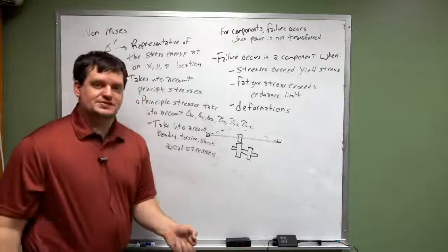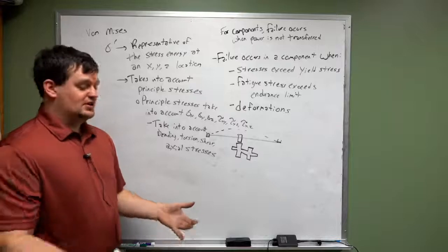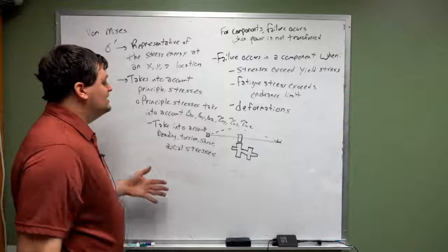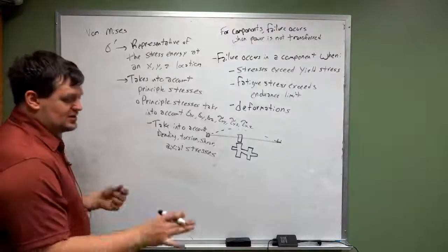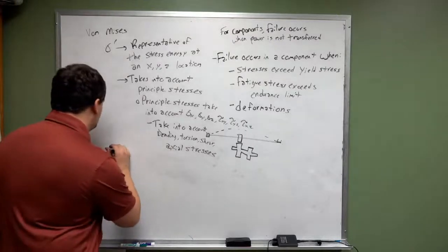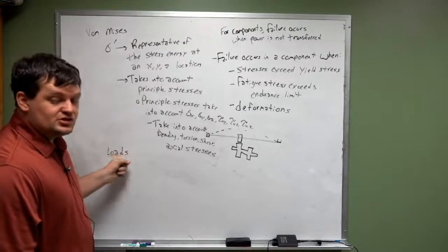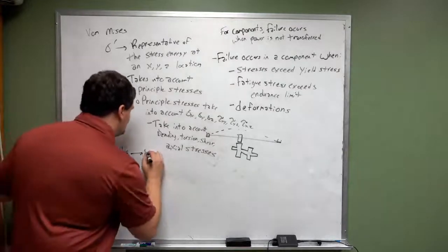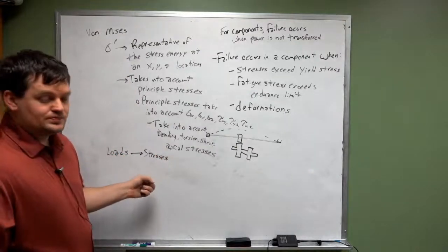That creates stresses. And each of these comes from individual loading conditions. Understanding what the bending is in multiple directions, understanding what the torsion is, okay? It's very much a process. I drew up this diagram early on in the semester. It's still applicable here. You come up with your loads, okay? This is bending loads, this is shear loads, torsion loads, axial loads. From these loads, you figure out your stresses that are directly caused by those loads.